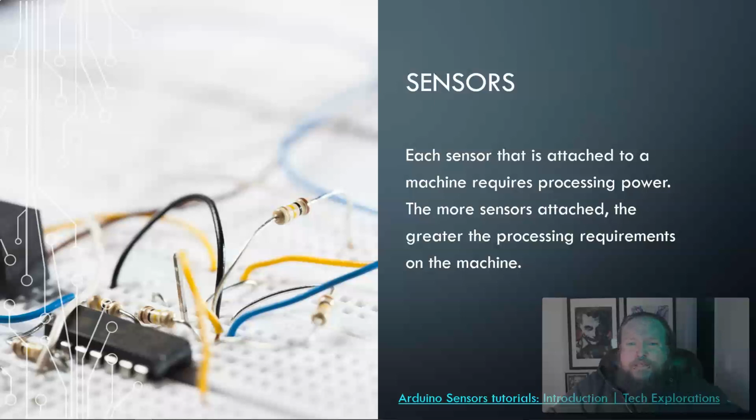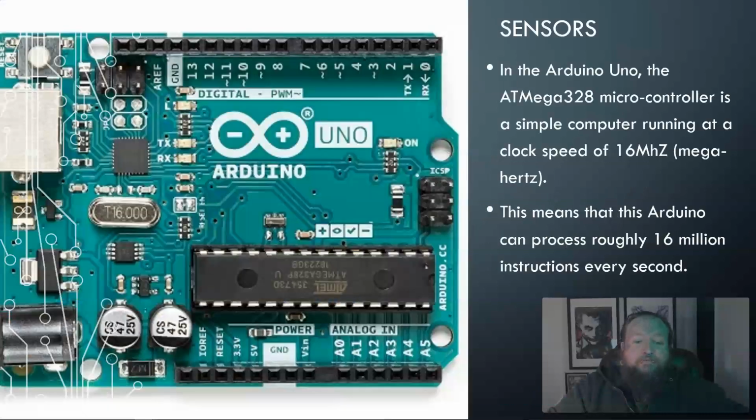And you need to also integrate it: how often am I reading from that sensor? How long is this task taking to get completed? What does it take to do that work and that kind of processing? So you need to take into account, if I'm adding in the sensor, what delays and time and processing is this also adding up? What power is adding up?